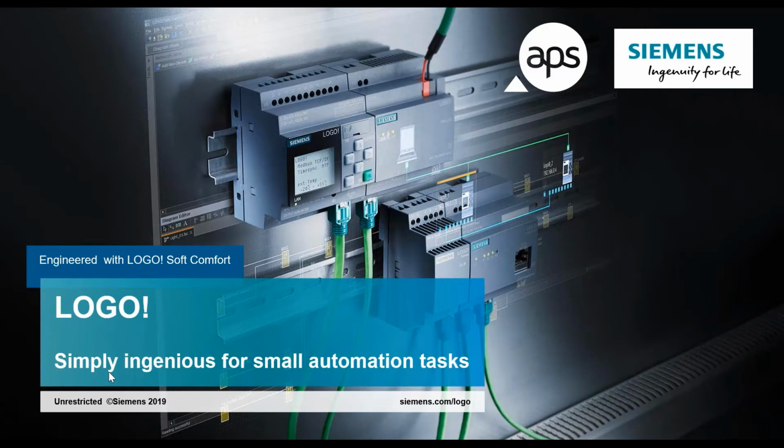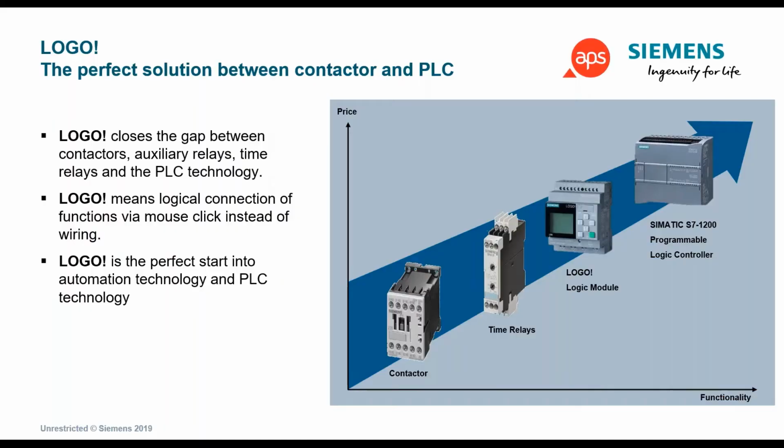With regards to the LOGO itself, we've indicated that it is what we call a logic device. Logic comes from the fact that you actually build it up out of logic. It can either be programmed in the form of function block diagram or alternatively as a ladder diagram. It's an intuitive device performance-wise. As mentioned prior to this, it is a smart relay, slightly more expensive than a standard contactor or a timer, but does not have the capabilities of an S7-1200, which is its bigger brother.